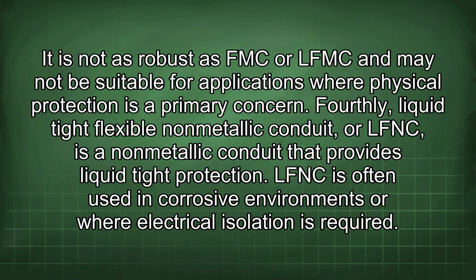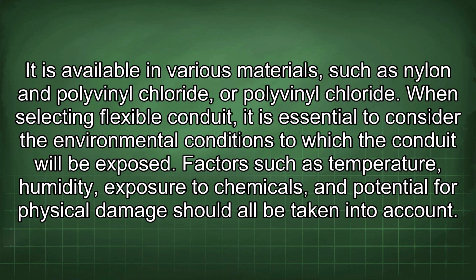Fourthly, liquid-tight flexible non-metallic conduit, or LFNC, is a non-metallic conduit that provides liquid-tight protection. LFNC is often used in corrosive environments or where electrical isolation is required. It is available in various materials, such as nylon and polyvinyl chloride.